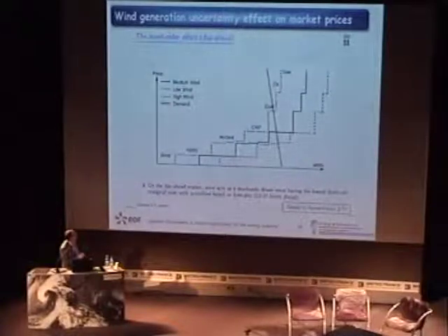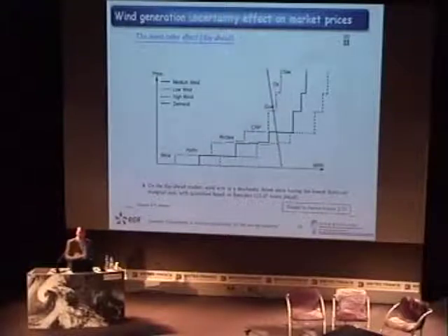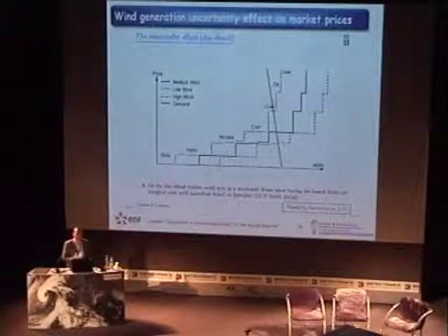And so you can see that you can have, for instance, this picture with wind, hydros, nuclear, combined heat and power, and so on. And if you have a large uncertainty on the wind forecast, on the wind power which will be available, of course it can move your curve to the left or to the right, and the effect is that it can totally change the production means that you will have to call to face your demand. In the blue case, the most expensive one will be the CHP, and if the wind blows a lot, you will use only nuclear, which is much cheaper, but if the wind blows at lower wind speed, you will have to use more expensive production means. And so even for a 24-hour forecast, the uncertainty in wind production can have a big impact on the energy prices, depending on the different means of production you will call to face the demand.